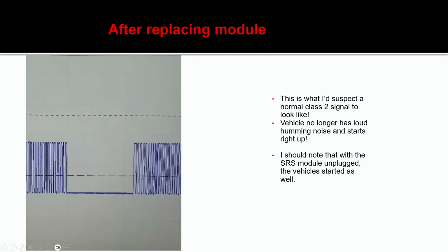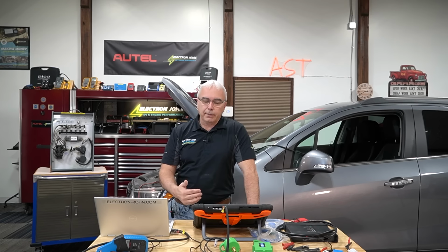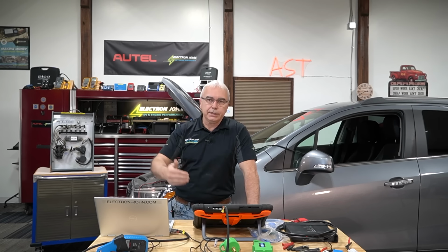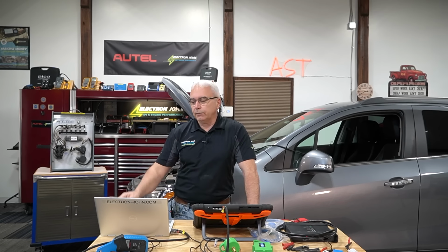But this was my mindset as to how to diagnose this. It all started with the customer call, and obviously verified the complaint. I hooked up a scan tool. That's always one of my first steps. When I had no communication, then I went to my scope. And then once I got my scope involved, I started to see the diagnostic process unfold in front of me here.